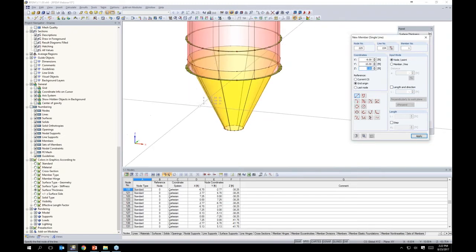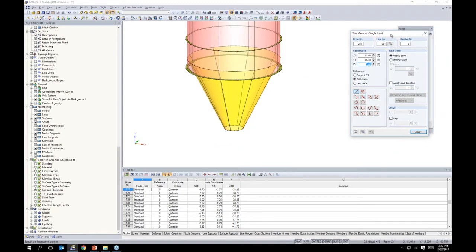Now we could utilize our drawing grid here and snap from 2 points, change the plane, but I want to show you guys some useful features again today that make our lives a little bit easier. For example, we can just easily specify the length and direction of this column as 8 feet for the length, perpendicular to the work plane in the negative direction.